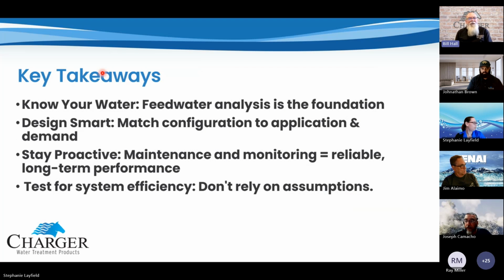You've got to monitor it. It's got to be very precise. You don't want to overdose it. You don't want to underdose it. So again, with commercial RO, you're going to have somebody there pretty much tweaking this system. It's not something that you can put in and walk away from. If you think you're going to put in a commercial system and wash your hands of it and say, okay, I'm done, probably not realistic. Somebody's going to have to monitor that thing. Somebody's going to have to tweak it. Somebody's going to have to keep an eye on things. And an ozone injection system would certainly be one of those.